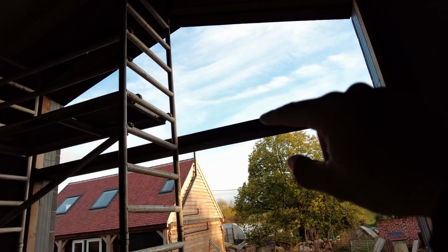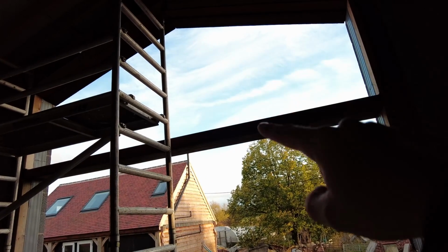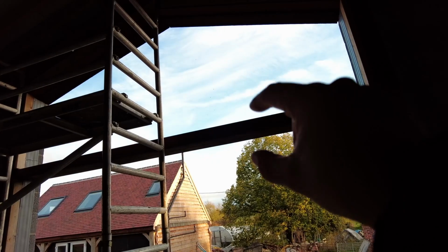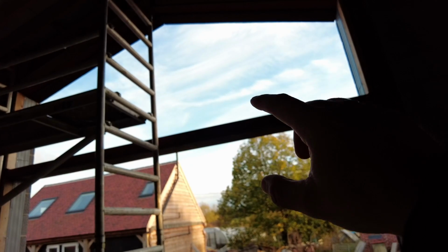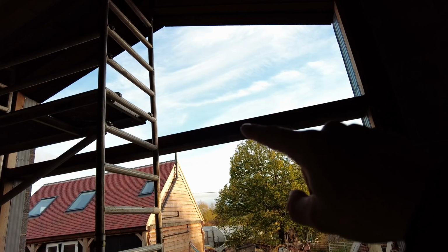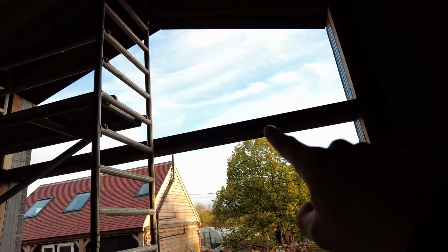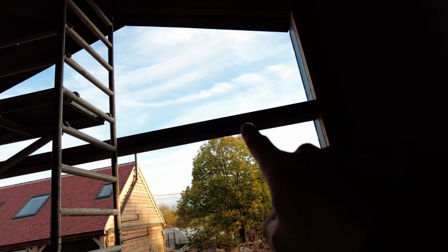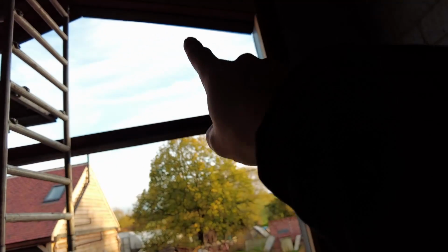So you can get them to line up the mullions exactly, but what you need to consider, I've got this big steel here. So between that, the gable window and the bifolds, plus the insulation, you're going to have a minimum of 150 mil between the two. Now, yes, you could line them up exactly. You would have to eye it straight on to actually notice it. But if you was to line it up exactly, the visible glazing between these ones would all be different.